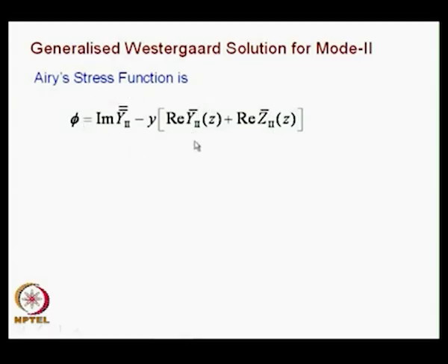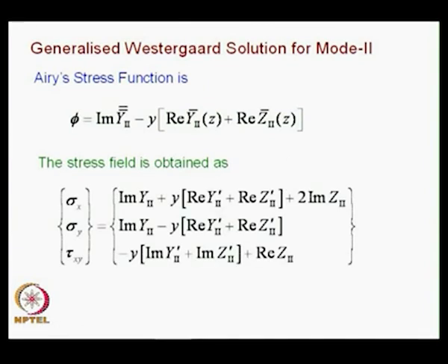These two terms are additional. Once the Airy stress function is defined, it is possible for you to get the stress field, and I would write the stress field in the form of stress functions only. I have sigma x, sigma y, tau xy, and sigma x is given as imaginary part of Y2 plus y multiplied by real part of Y2 prime plus real part of Z2 prime plus 2 imaginary part of Z2,